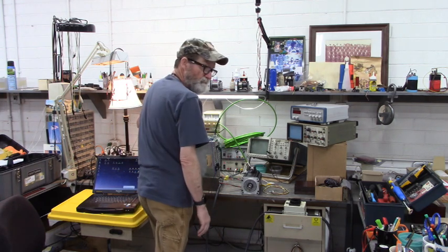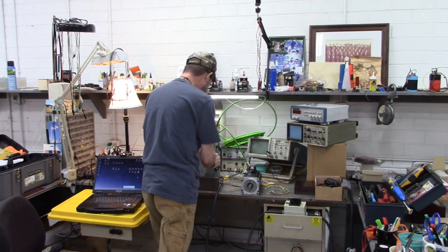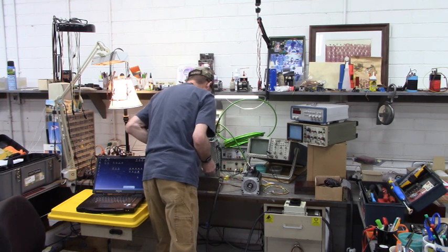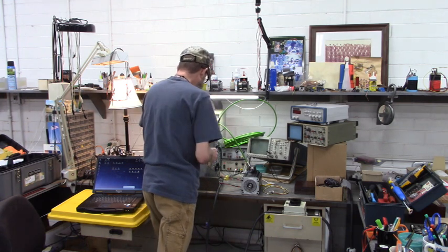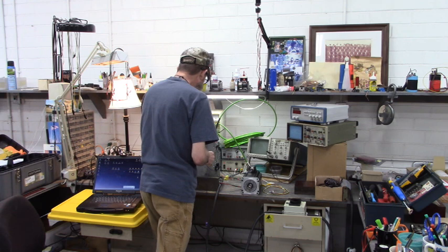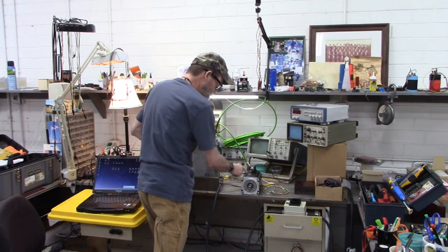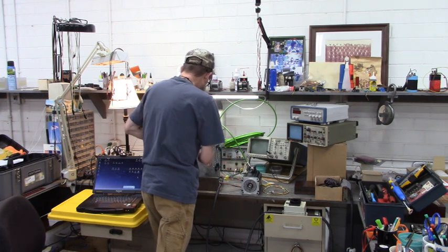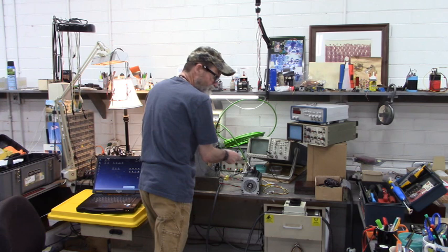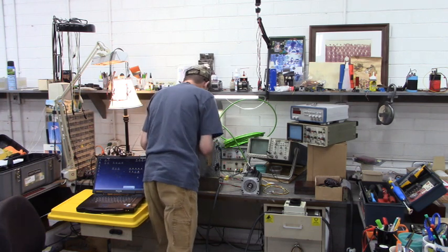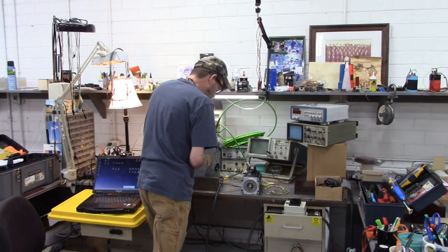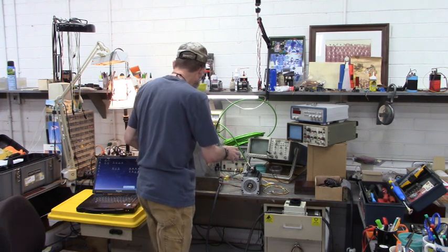Okay, the drive comes up to AB in the 7-segment display, and we're going to connect the RF terminal to plus 24 volts DC. Okay, the brake has been released. There's an electromechanical brake inside this motor. The drive releases that brake when you connect the RF terminal to plus 24 volts. Now we're going to connect the AH terminal to plus 24 volts. And we're moving. We have a good system here.